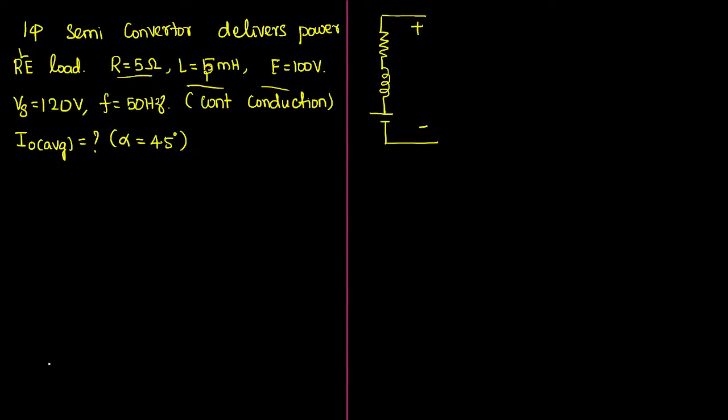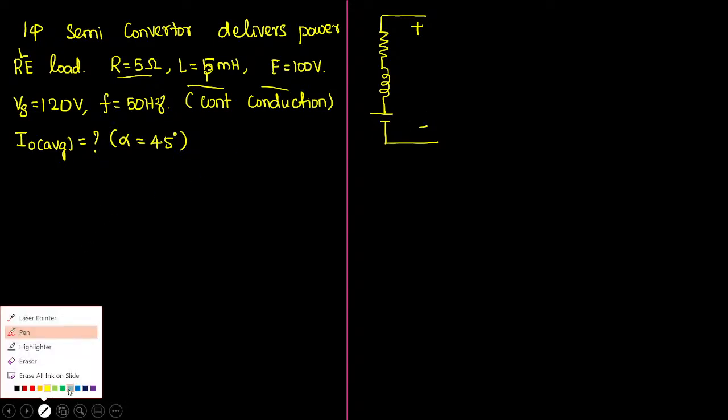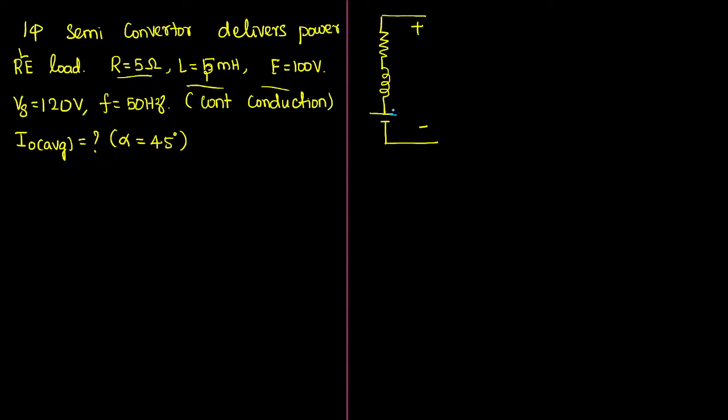But what did I tell you? I told you when a DC supply is connected in series, the inductor will behave as a short circuit. So we can draw its equivalent circuit like this. You can consider one resistor and one battery. Simply, 1.547 ampere. Geeta, very good.